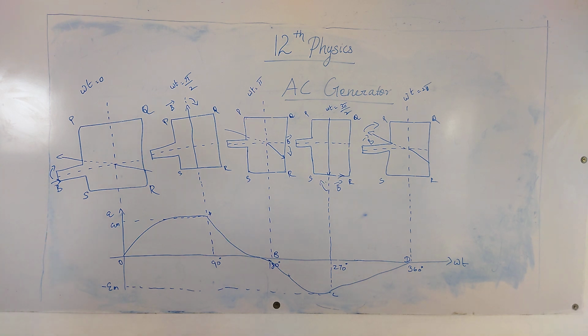Then we see about the rotor. The rotor contains the magnetic field winding. The magnetic poles are magnetized by a DC source. The ends of the field windings are attached to a pair of slip rings. Then the slip rings are connected to two brushes. Then we see the advantages of a stationary armature, rotating field alternator. Here the current is drawn directly from the fixed terminal on the stator without the use of brush contact.